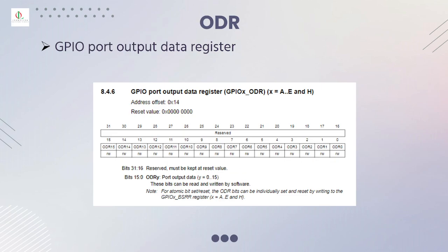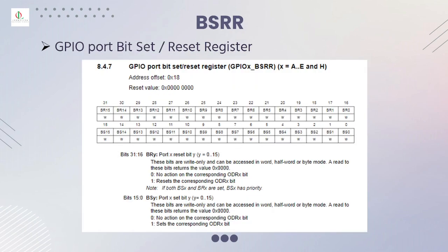And the output data register, you're going to connect all the output data registers, that's from D0 to D7. You will learn how you're going to connect that in the program that's coming up. Then you also need to use the BSRR, the bit set or reset register. This is for the read/write, register select, and the enable. So you've got to choose these 3 pins, which I will show you in the program, and set them as enabled so you can use those 3 pins.